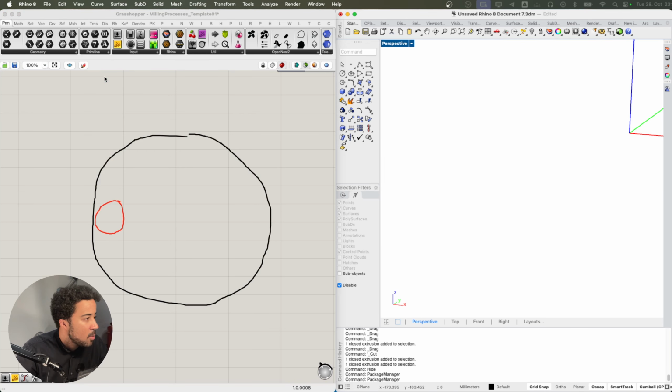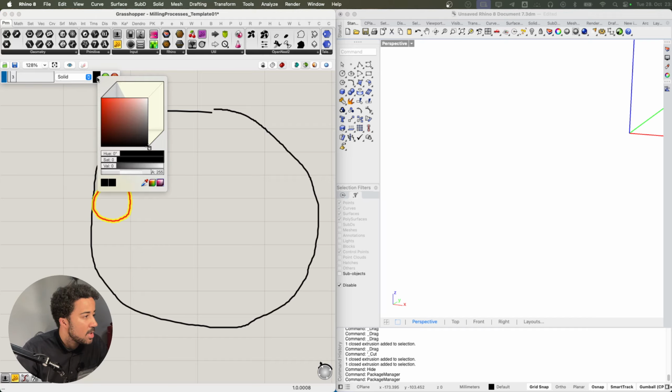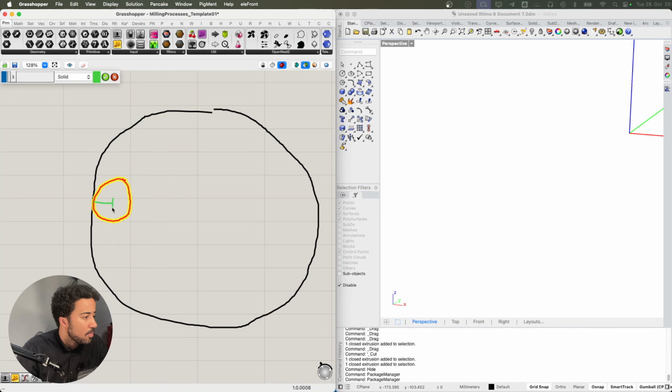So imagine the cutting tool having this diameter. And of course, we don't want to simply have our cutting tool cut on the outside of this circle. We want it to be offset to the inside by a specific amount, and that is just the radius, or half of the diameter, of our cutting tool width. So this is our first offset. So our first curve goes along the circle at this distance.